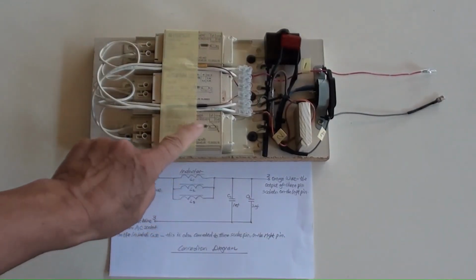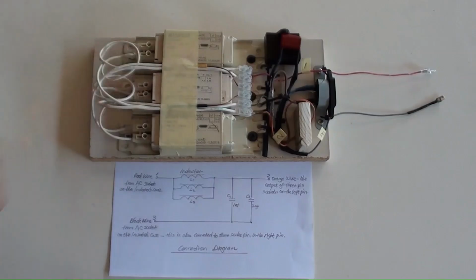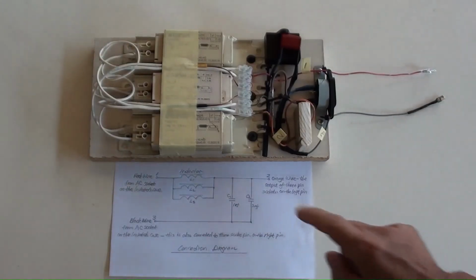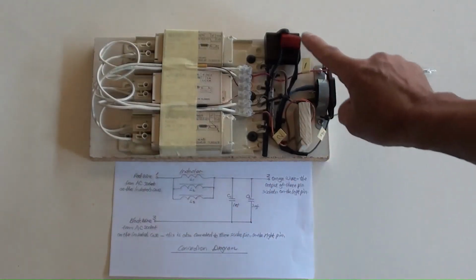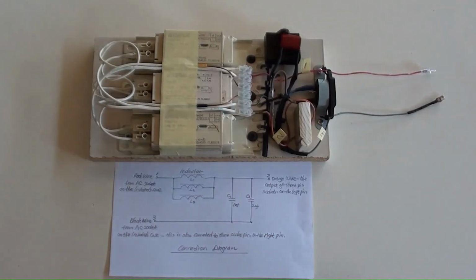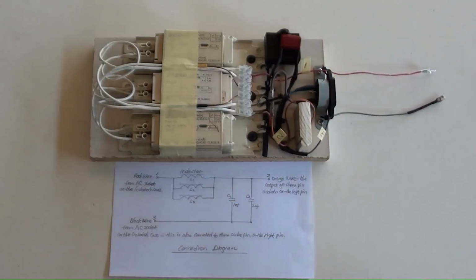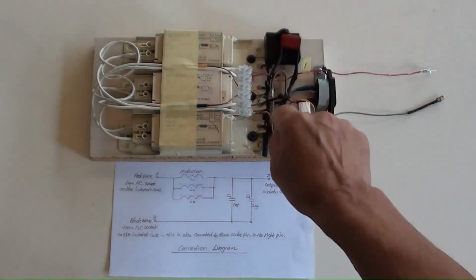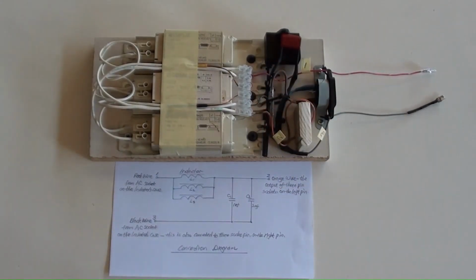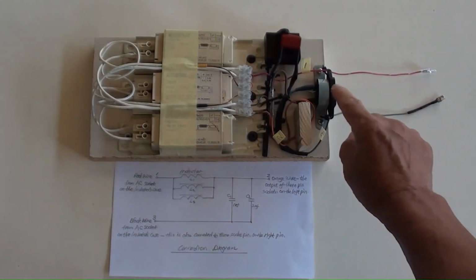Three inductors connected in parallel secured along here. Chosen 2 capacitors in parallel combined. And 1 μF capacitor is there, and underneath it is a capacitor with 2 μF, total of 3 μF, and 400 volt rated. The wires connected are looped here. The output of AC 240 volt socket is secured there.